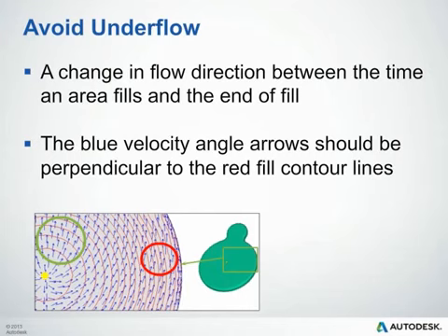Molecules want to generally shrink more in the direction of the orientation. And so, if there's underflow, there is significant internal stress in the location of the underflow.